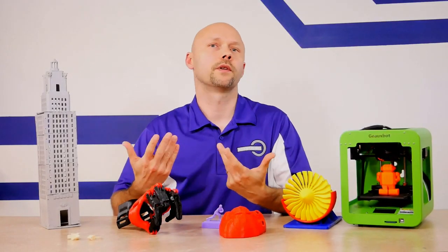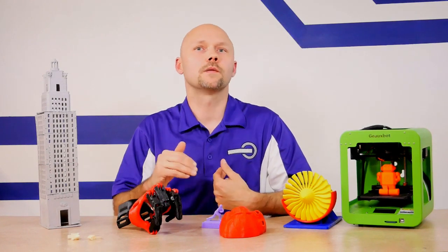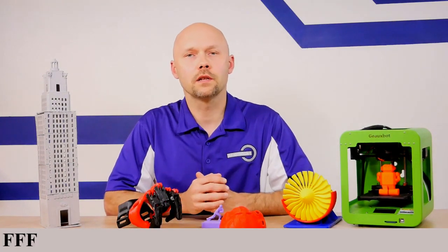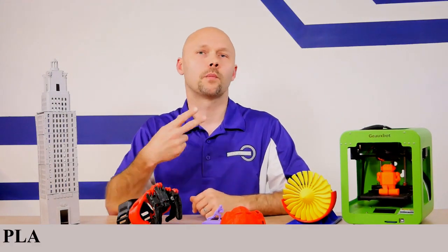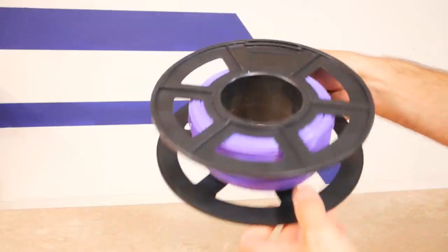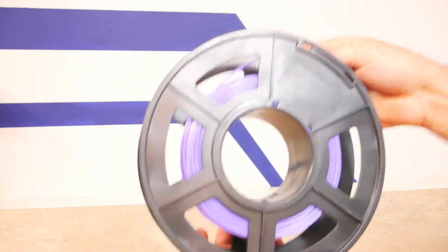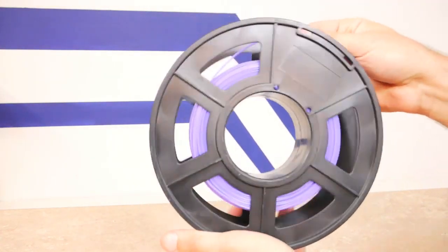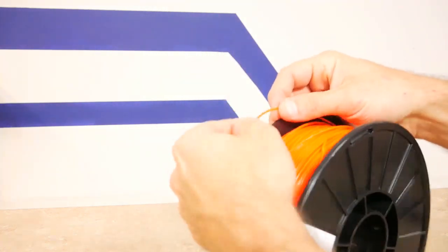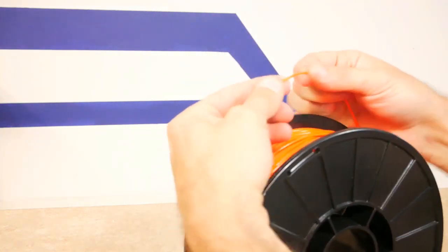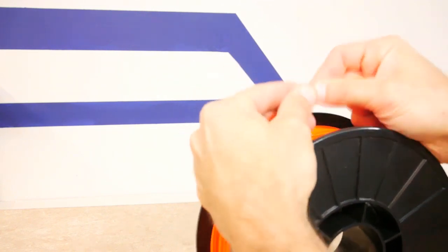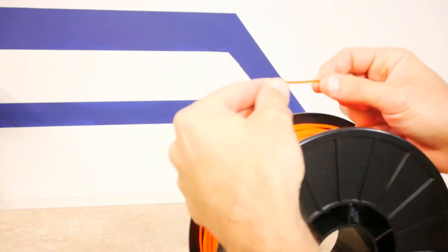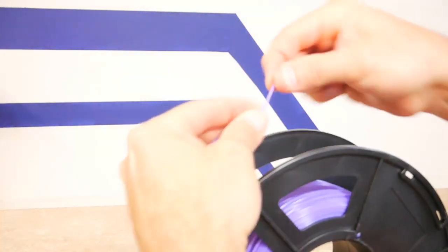So some of the materials in 3D printing. Now, the 3D printers we're talking about, the FFF, fused filament fabrication, use plastic for the most part. There are many different types, but the main two are PLA and ABS. PLA is a biodegradable plastic. It's a lot safer to use. It doesn't have any odor. ABS, which is what Legos are made from, does have somewhat of an odor and is a bit trickier to 3D print. Now, each has their own uses. ABS is a little bit stronger than PLA, but to each his own.